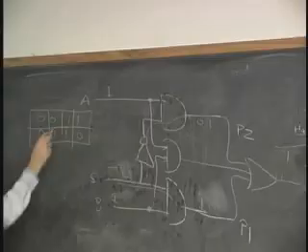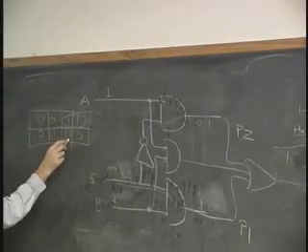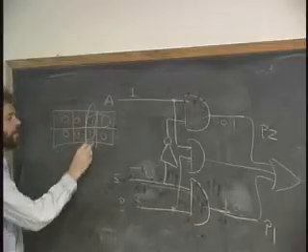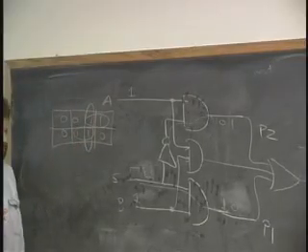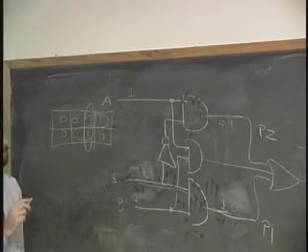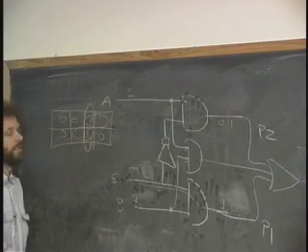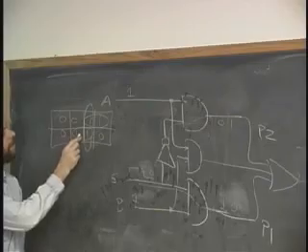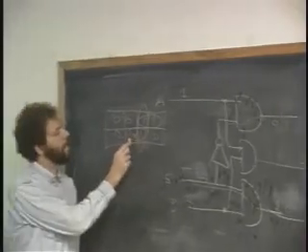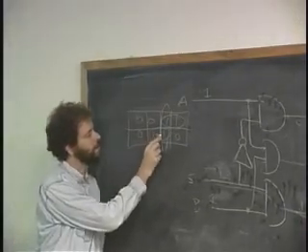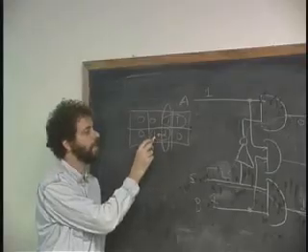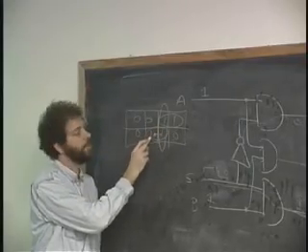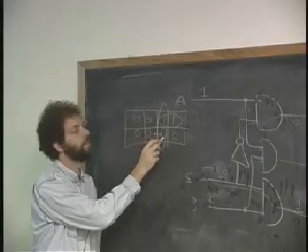Like so. I used to go like this, I used to go like this, and now I'm going to put in another one that looks like this. You remember the rule of the K-map was that if I change one input, I move across one boundary. And what I'm saying here is that if the output is high and one input changes, I move across this boundary, but I stay within the confines of an AND gate that is not sensitive to the change.